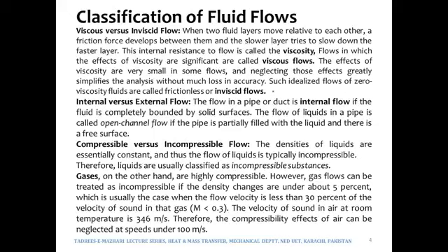However, there would always be friction between the layers of the fluids. So in reality, the flows would be viscous. However, sometimes they are assumed as inviscid flows to make some simplifications and make things easier. Internal versus external flow has already been discussed. Compressible versus incompressible flow: it depends upon the density.